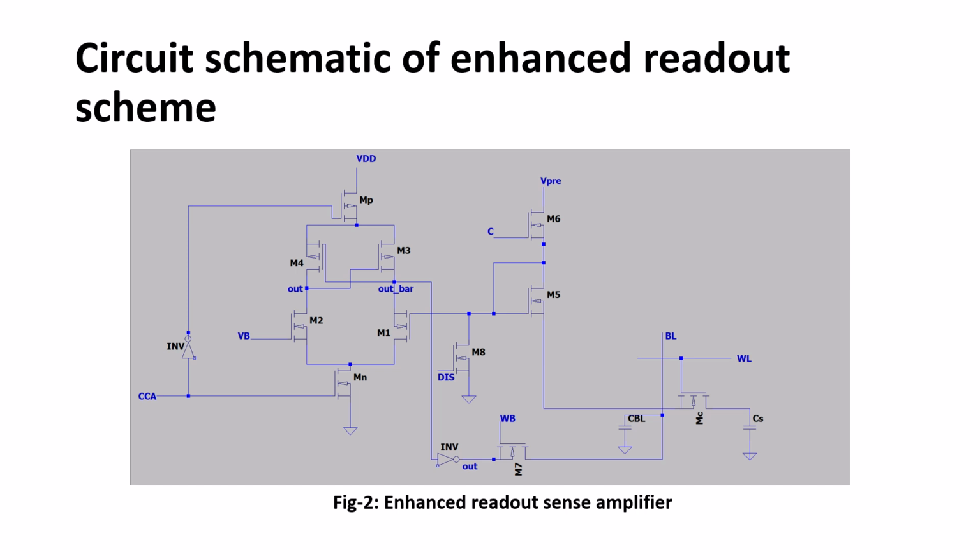The V gate of this transistor is going to increase in order to compensate this source node voltage, to maintain proper equal currents from the M6 and M5 transistors. As we are storing VDD across the storage node capacitance, whatever voltage develops over here will decrease the VGS, as a result of which the current through this M5 decreases. In order to accommodate the same current, this VG has to increase to balance out both currents.